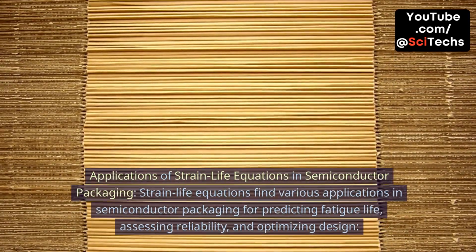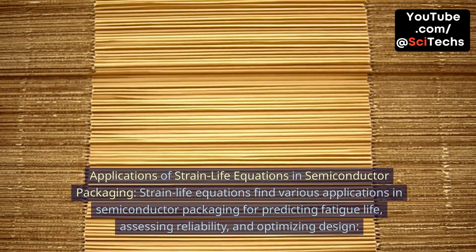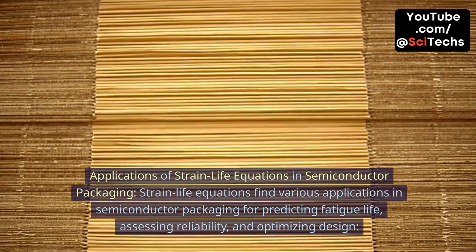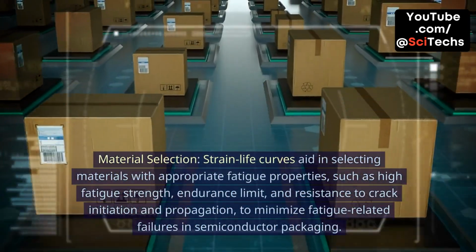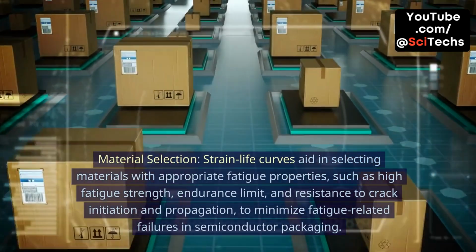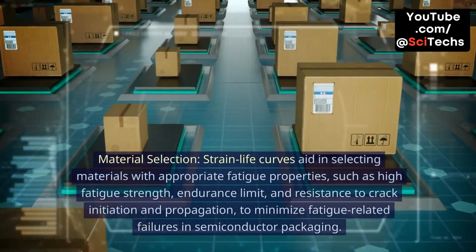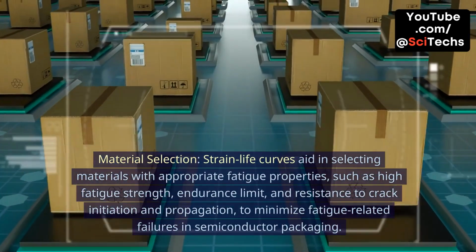Applications of strain life equations in semiconductor packaging. Strain life equations find various applications in semiconductor packaging for predicting fatigue life, assessing reliability, and optimizing design. Material selection. Strain life curves aid in selecting materials with appropriate fatigue properties, such as high fatigue strength, endurance limit, and resistance to crack initiation and propagation, to minimize fatigue-related failures in semiconductor packaging.